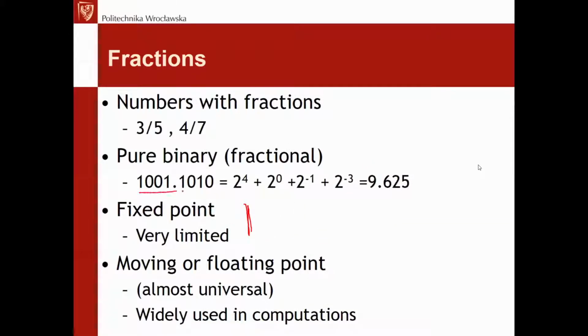Here you have an example of this binary read as a fractional. This is the binary of hexadecimal 9A. Of course, we can read it with a sign, or without a sign. We can't read it as BCD, by the way, because A is 10, so this symbol is forbidden.